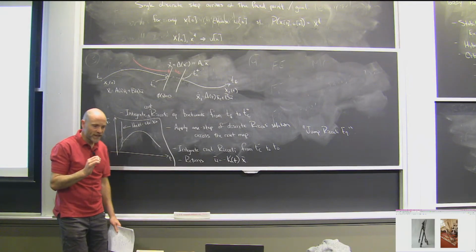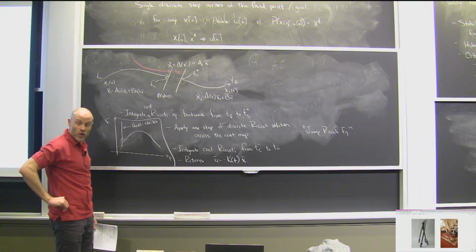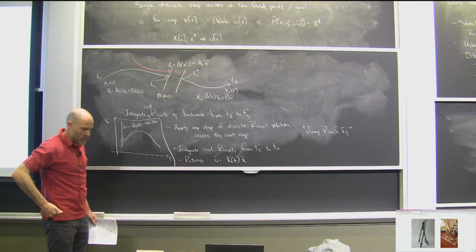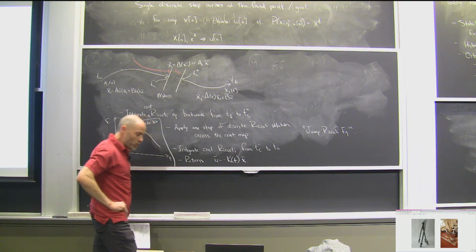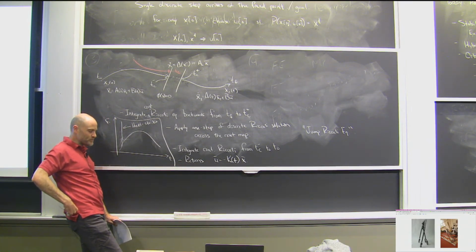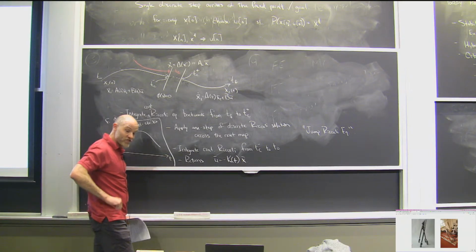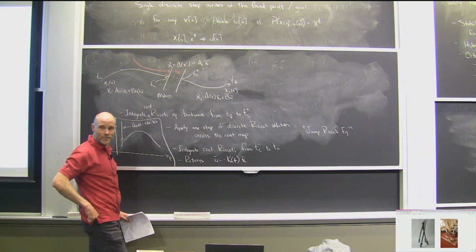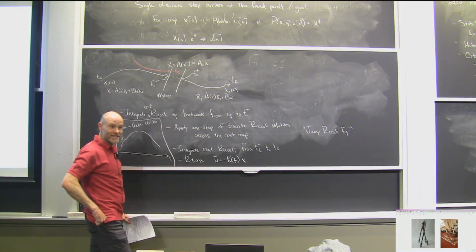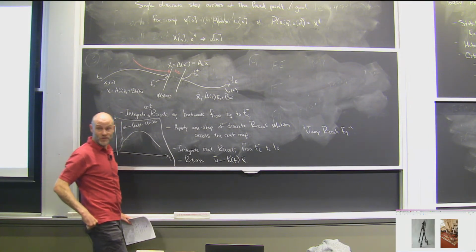Because the only actuator in the compass gait was an actuator at the hip. The way that you want to stabilize a trajectory implies applying a torque at the hip. And the sign of the torque at the hip is exactly opposite if you're pre-collision or post-collision, right?